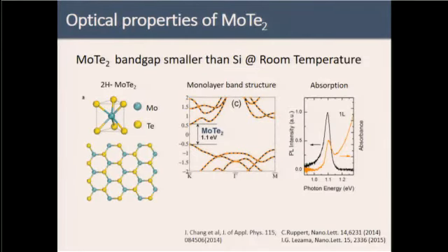Recently, it has been noticed that in a lot of 2D materials, when they go to atomic thin layers, they become direct band gap semiconductors, and they have very good quantum yield. But for example, for tungsten sulfide and molybdenum disulfide, their band gap is kind of large. The photon emitted is mostly in the visible range. So when they are combined with silicon photonics, their emitted photons will be reabsorbed by the silicon. That's why those materials do not work.